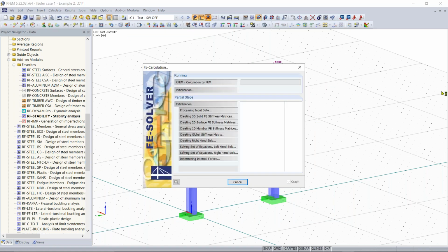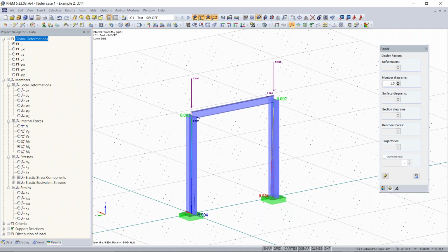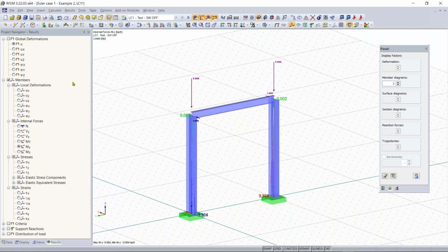I see there is a question. Yeah, so we have a question saying, is it by default the analysis will segmentize the column into 12 smaller segments? I counted 12 roughly on the string, could be wrong. And this all comes down to essentially just the settings within the calculation parameters of how a beam is divided. For this one, you can place FE mesh along the straight elements. So under FE mesh settings. Right, yep.